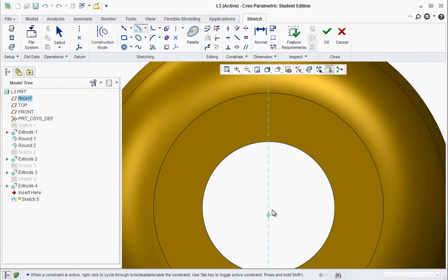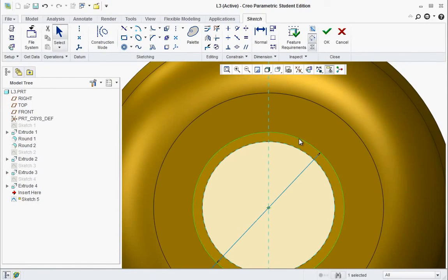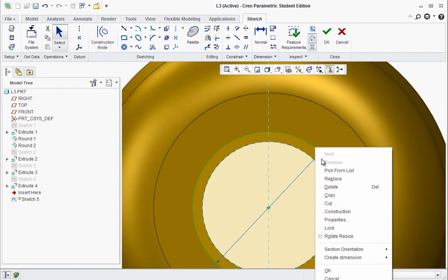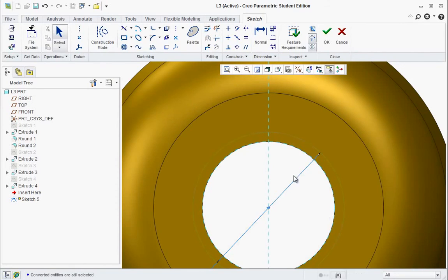And normally it's kind of hard to, actually we'll just use the concentric circle. Select the edge, drag out a small circle, a little bit larger than the internal diameter, click, then middle click. Change that circle to construction by right-clicking on it. And now we can use that with our text tool.